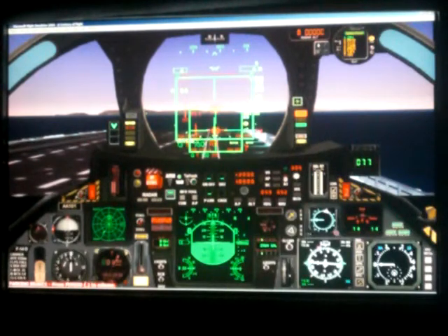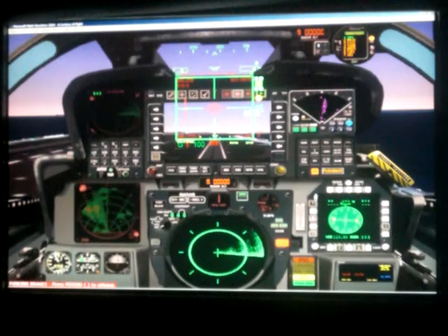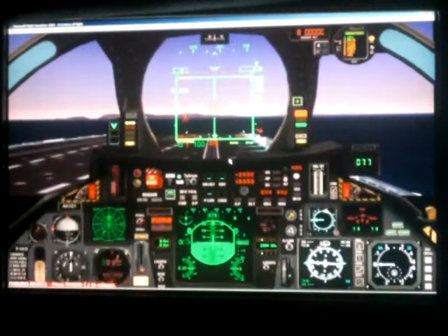I can turn this meatball off, but you see the Rio one is still on, so I need to go back to the Rio seat, hit meatball right here to turn that off, toggle back to the main panel. Now you can see the meatball, and then I would have to use this gauge up here to select which carrier I'm operating from, which in this case is Puerto Rico. And then once I get on the glide slope, this will work.